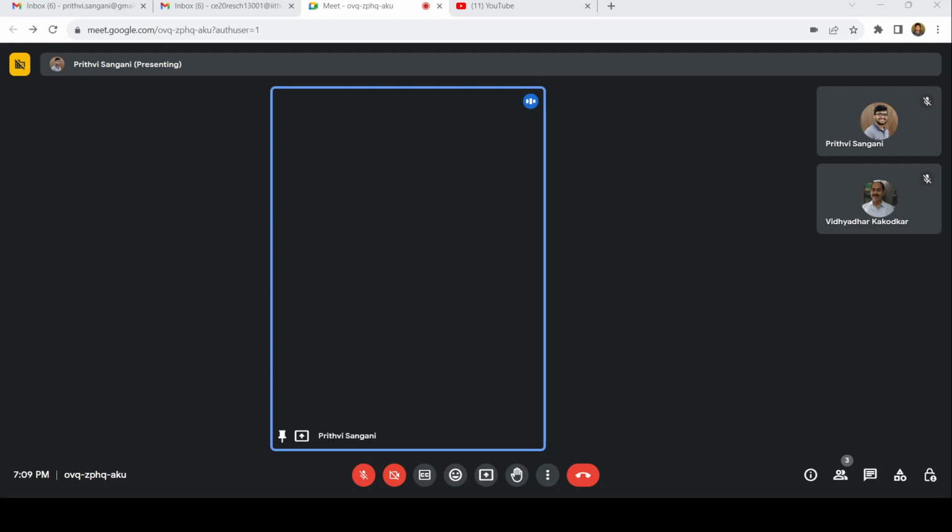Now what is the compatibility condition? The compatibility condition is delta 1, and this should be an algebraic sum. Even though we assumed delta 1 in this direction, it is minus, so minus is actually in this direction. If this is positive, it is going to be in this direction.